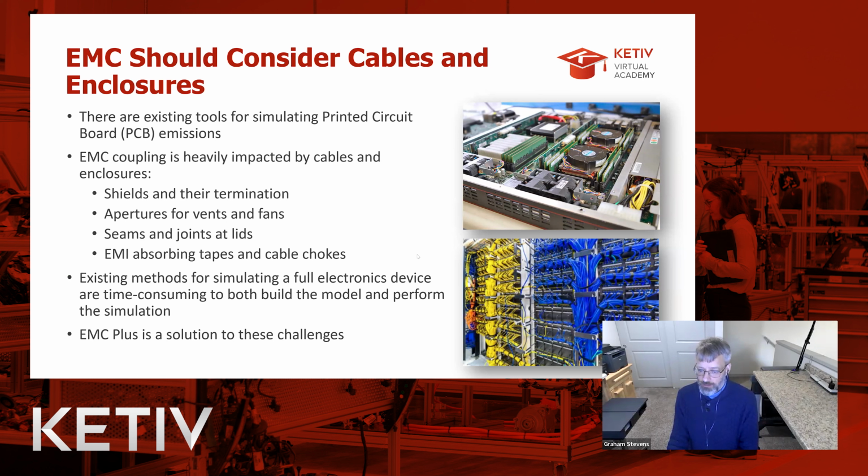One thing we've noticed with EMC simulations is that cables and enclosures are a very important part of this picture. So we have existing tools for printed circuit board emissions. HFSS can do that, as well as in particular SI Wave. But you really need to consider the cables.